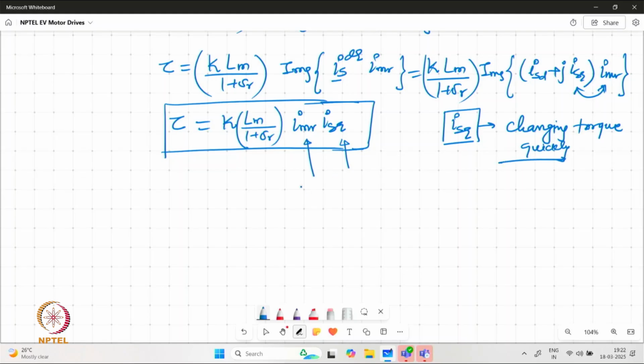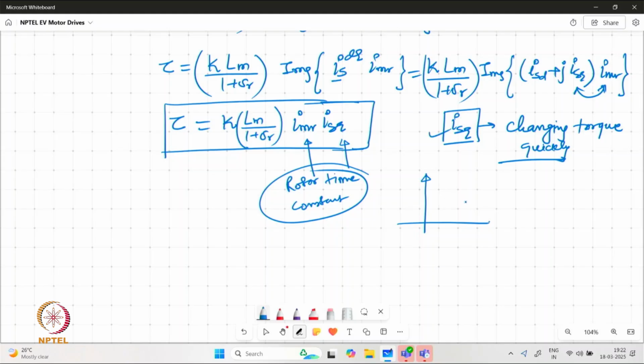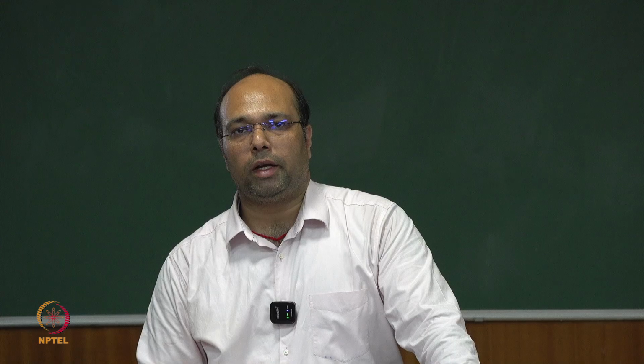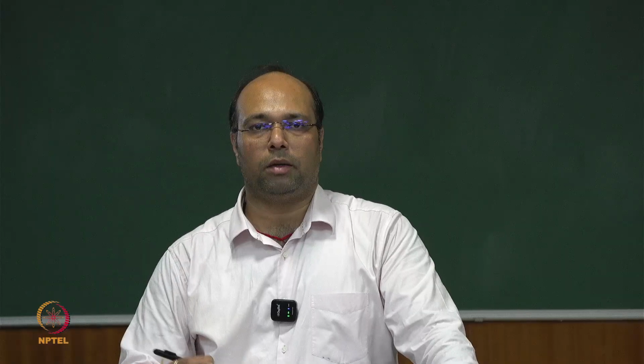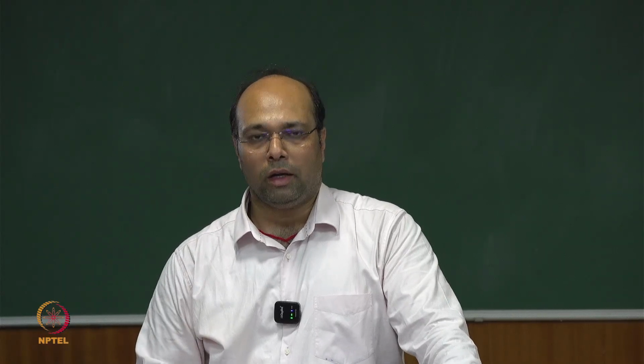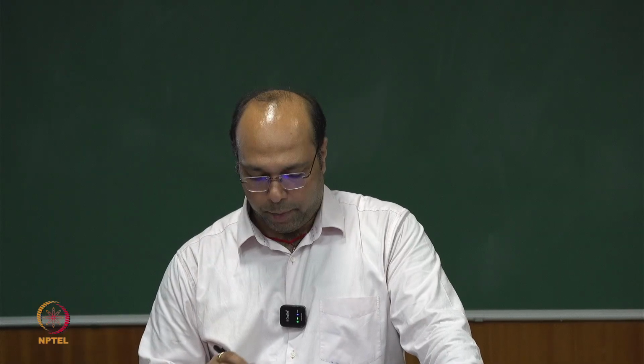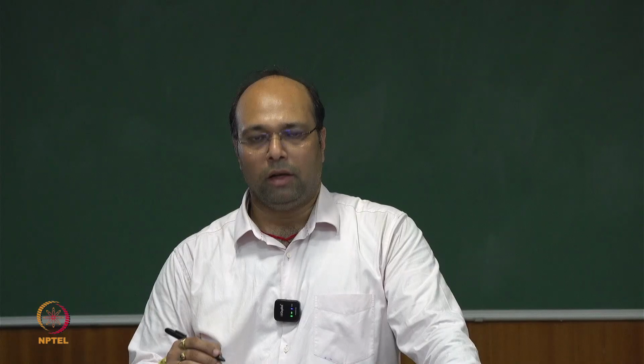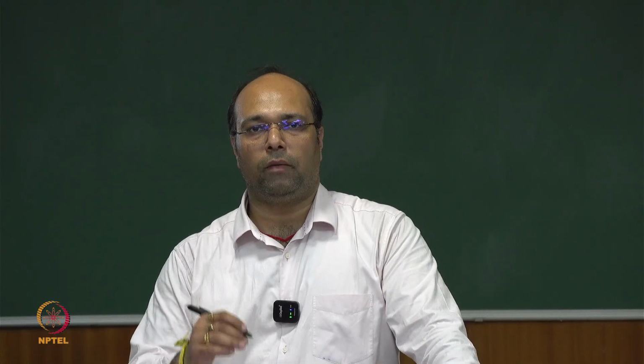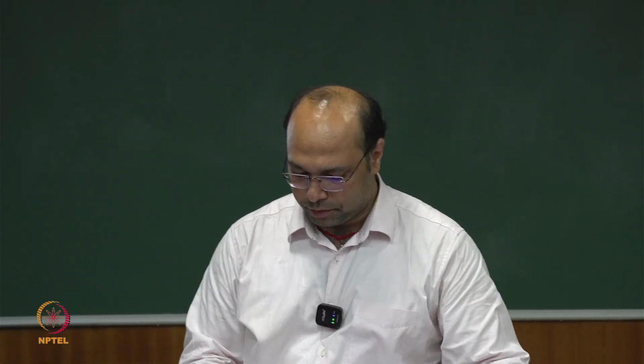We understand that there is a rotor time constant involved with IMR. Therefore, IMR is sluggish in nature compared to ISD and ISQ. So, which is why many a times when we are asked to change the torque in the machine in vector control, we naturally choose ISQ for doing that. And by keeping IMR constant, we maintain a good value of the flux and then play with the value of ISQ to achieve the desired torque in the machine.